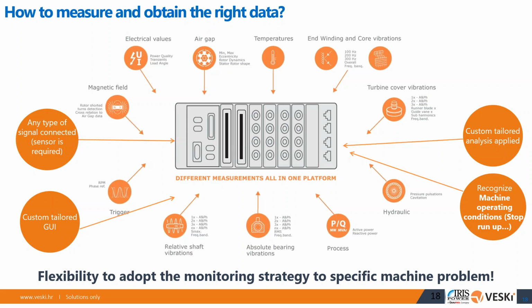Because for low frequencies, you need a longer signal to be able to extract them accurately. If your signal is too short, you just don't see the frequencies below the duration of your signal. So these machines can vibrate at 0.5 hertz, which is a very low frequency, and they can spin at, let's say, 3 hertz, which is 6 times more. So if you want to catch that, you need to have a longer period of signal.